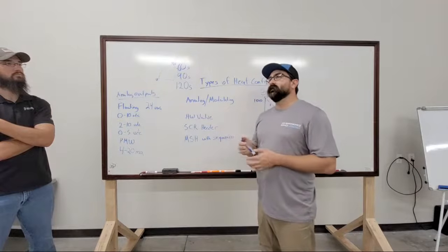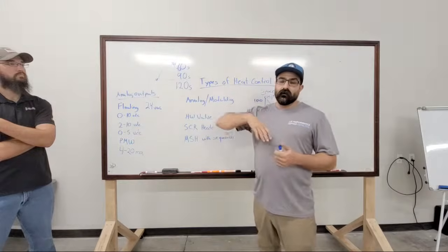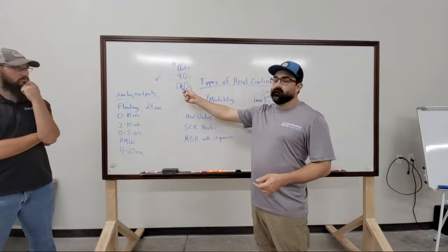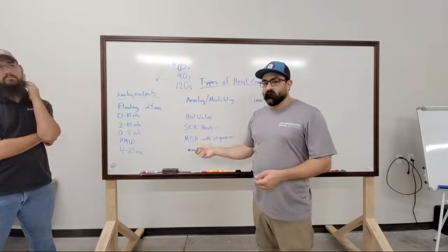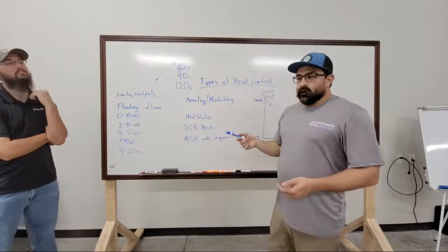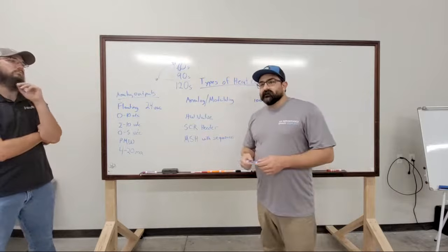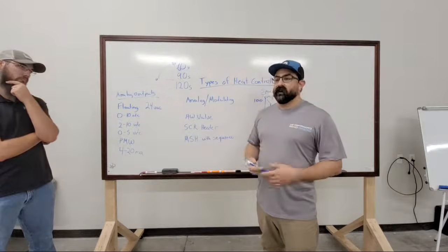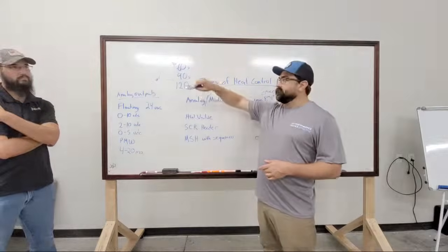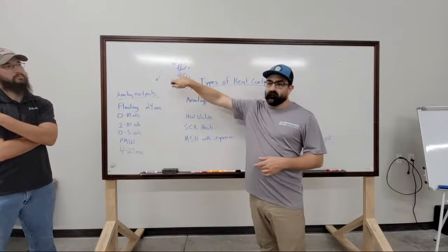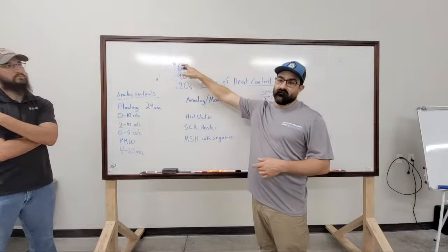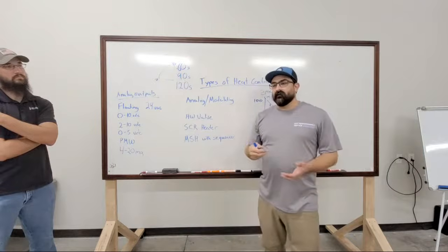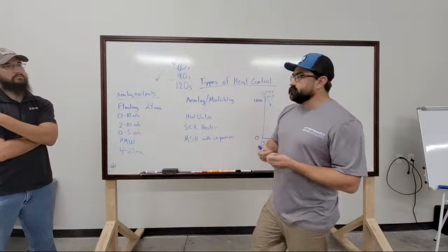When I say resynced, we typically either sync open or sync closed. You'll send them voltage for a period of time greater than your travel time to ensure that it goes all the way to whatever position you wanted. Usually the safest bet is to sync closed, because not every system will open 90 degrees. Some of them only open 45, so we have to change these travel times. If I have a system that's full open at 45 degrees, then I would only run this damper for 30 seconds, or this one for 45, or this one for 60, based on that percentage of open at full.